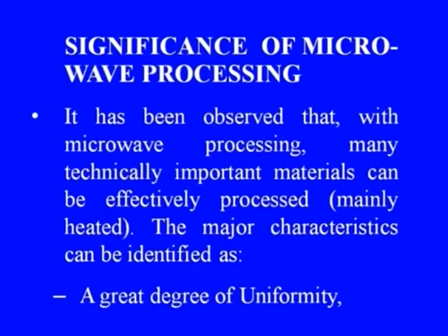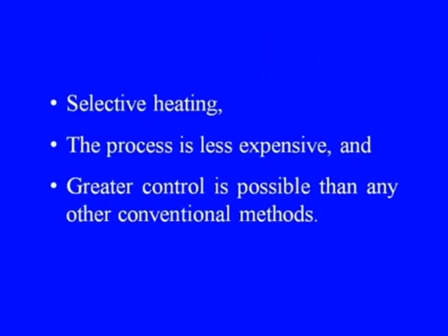Significance of microwave processing. It has been observed that with microwave processing, many technically important materials can be effectively processed, mainly heated. The major characteristics can be identified as a great degree of uniformity, selective heating, the process is less expensive, and greater control is possible than any other conventional methods.